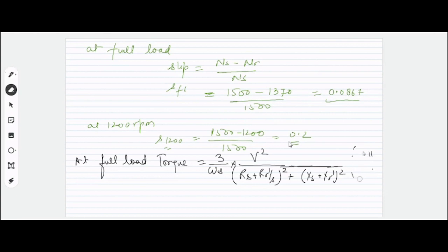Tell me, how much will be the torque value? Torque at full load. This will be the torque at full load. Give me the answers. We know this value of slip. How much will be the value of slip for this case? It will be 0.0867, right? Because we are talking about the full load torque, that is TFL.